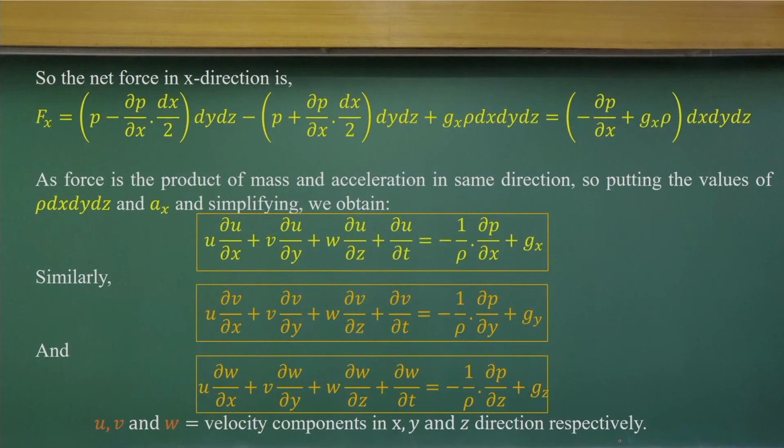That is the gravity force acting in the x direction on this control volume. If I equate it, the sum of the forces acting in the x direction will be this, as you can see from the force directions, and the g_x component is the gravity force. So the net force is this. That net force should be equal to mass times acceleration in the same coordinate direction. This is the acceleration part, and this is the force per unit mass, unit weight. This acceleration part has two components, local acceleration and convective acceleration in the u direction, equal to the two components.